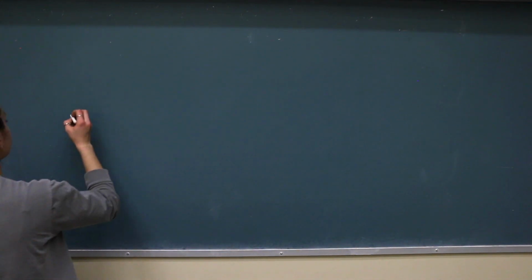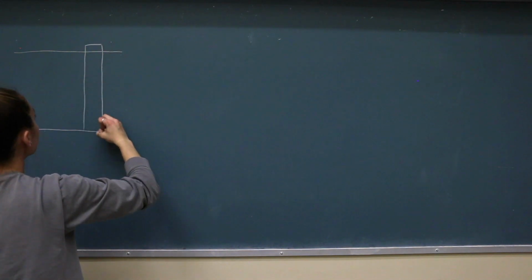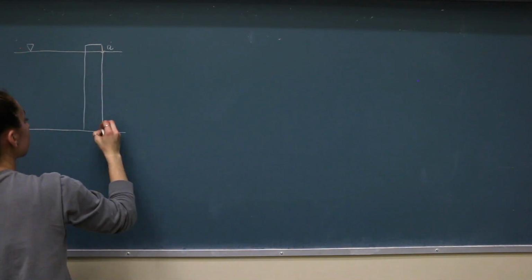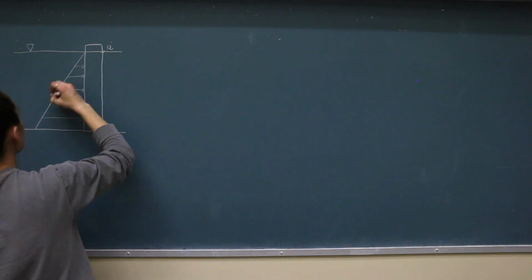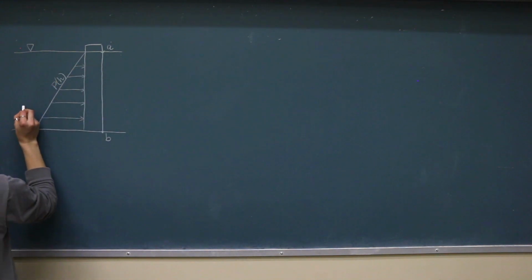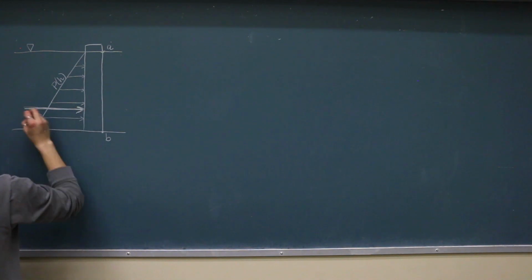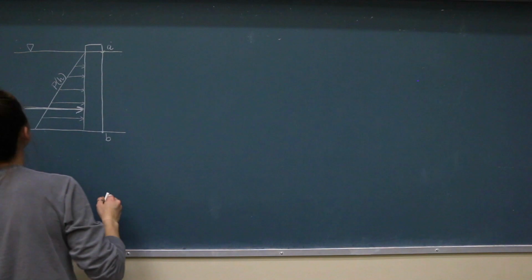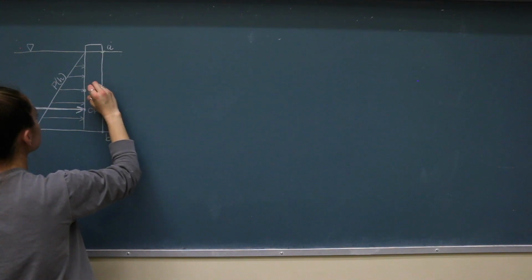Let's derive the resultant force and the center of pressure in a hydrostatic situation. As you can see here, a submerged wall experiences a linear pressure gradient from point A to point B along its submerged surface. This pressure gradient creates a resultant force, Fr, whose line of action is somewhere below the center of gravity. We call this point the center of pressure, or Cp.